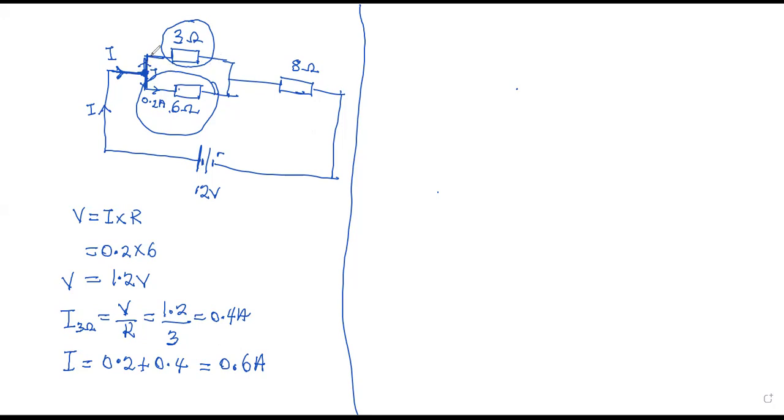Okay. Now, 0.6 current will divide into 0.4 and 0.2. Then they will combine again to leave this junction. Let's call this junction D. So 0.4, 0.2 would enter this junction, and the sum of it will be the same current leaving the junction D, meaning that the current that will flow through the 8 ohm resistor would be this.